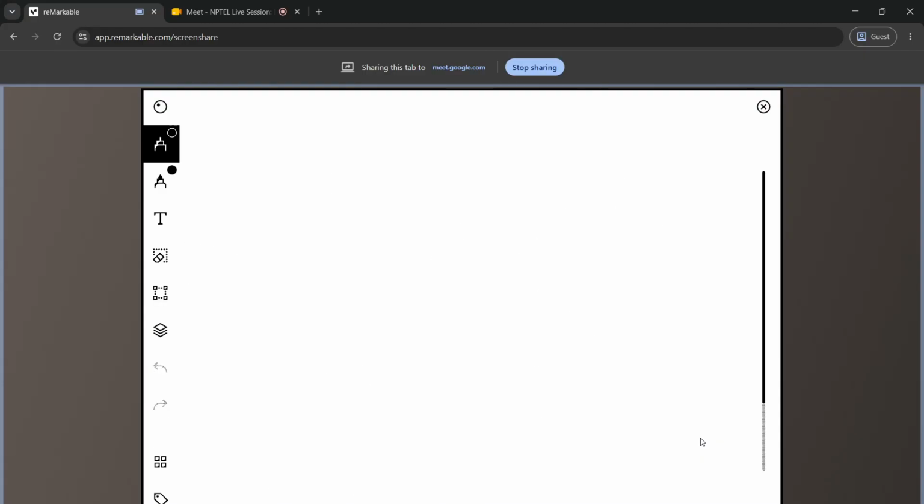So if you do the same for energy balance, we have the net heat flux given by, from 0 to delta plus delta star, we'll be having rho times u times, for energy balance, the quantity that is being conserved is enthalpy, which is given by Cp times T. This we have discussed in the first week of lecture videos. Minus the net incoming energy flux, from 0 to delta, rho u infinity, free stream velocity, times the specific heat times the free stream temperature. Now again from here it is same as before. So 0 to delta, I can take rho Cp out, and this Q is basically the net heat flux, that we'll get to in NPTEL 2.